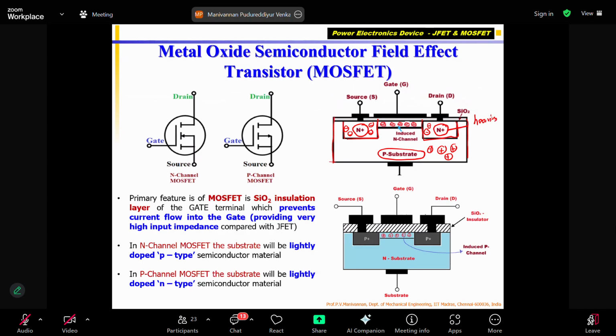Generally, you may ask, sir, what do you mean by N and N plus? I say N means N-type material, it has electrons. N plus means what? For example, if I say N material, for a given volume of this semiconductor material, as I told yesterday, there were 1,000 atoms originally, before doping the impurity, phosphorus, in the silicon material. I displaced 100 atoms with phosphorus atoms. So it became an N-type material because phosphorus atom has an extra electron in the outer orbit.